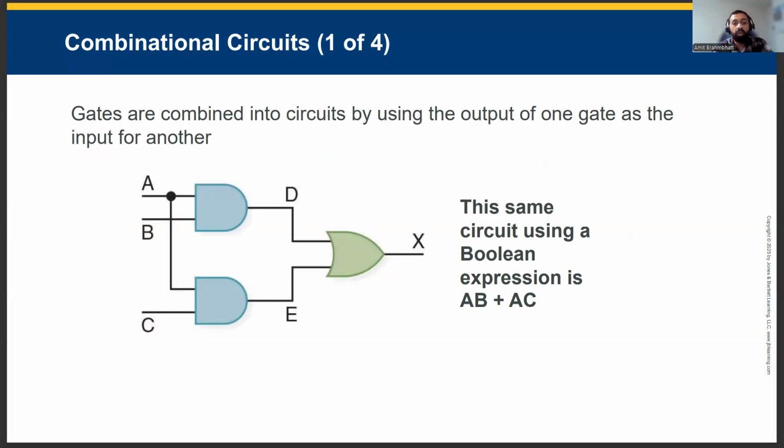Here is a small combinational example. We can wire gates so the output equals AB plus AC. Read A and B or A and C. In a diagram, you'll see A feeding two paths, one combining with B and another with C, and the two results ORed together. The Boolean expressions and the diagram say the same thing. Later, we'll confirm with a truth table.